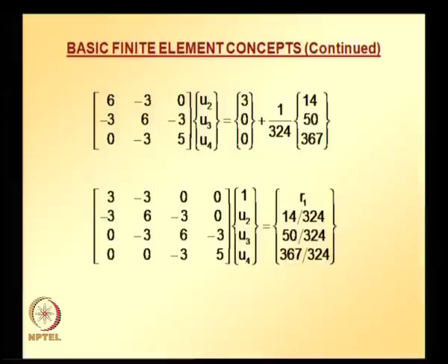using this idea, global equations obtained using variational method are identical to those obtained using Galerkin method, which you will see in a while. So, whatever procedure we are following here is the variational procedure, but you have seen from the examples that you looked at for classical approximate techniques that you get exactly the same solution if you adopt variational method or Galerkin method. Similarly here you get exactly the same equation system if you use the second approach, that is, wherever the essential boundary condition is known, at that location in the force vector you make that component unknown.